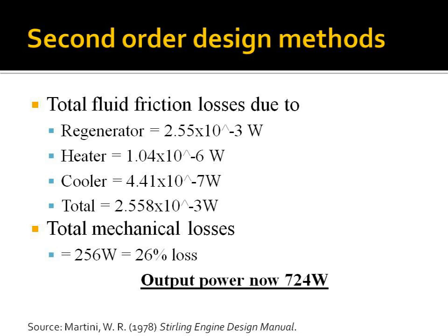But also there are analytical methods of researching experimental data. You really want to know what sort of crank mechanism you're going to be looking at, and then look at experimental data of what sort of mechanical losses a similar crank mechanism experienced, and that's an analytical way of determining your mechanical losses.